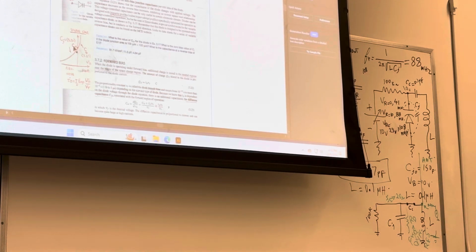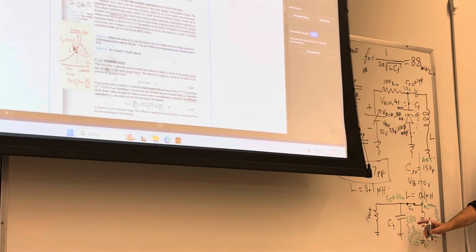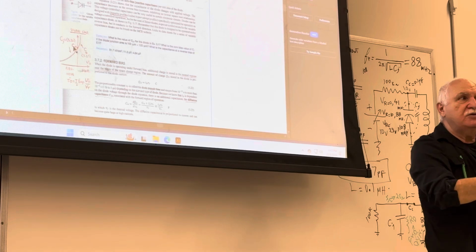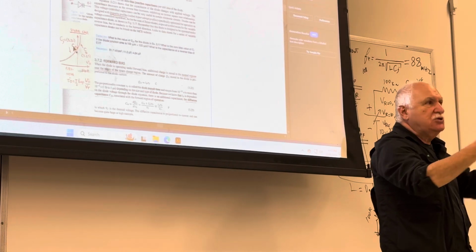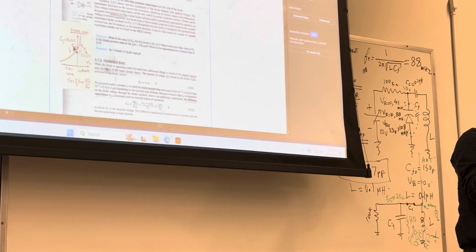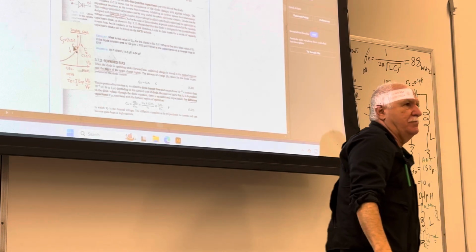Well, here's the problem. If you make a resonance circuit, LC, 10 or 20 ohm is a very low resistance that will not resonate for you. It's like that vase example I gave you. It's like loading a lot of energy absorbing material in the vase. When you hit it, it will not ring because water absorbs the vibration and energy. But in the other case, in the reverse, the diode does not consume, does not dissipate energy. Therefore, it causes the LC to resonate, and that's what we want.